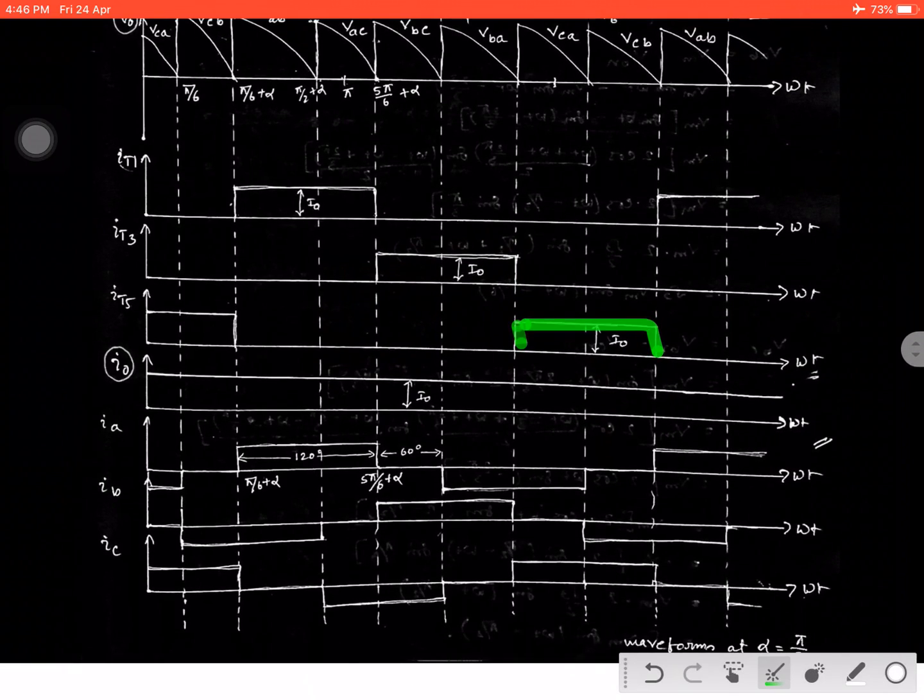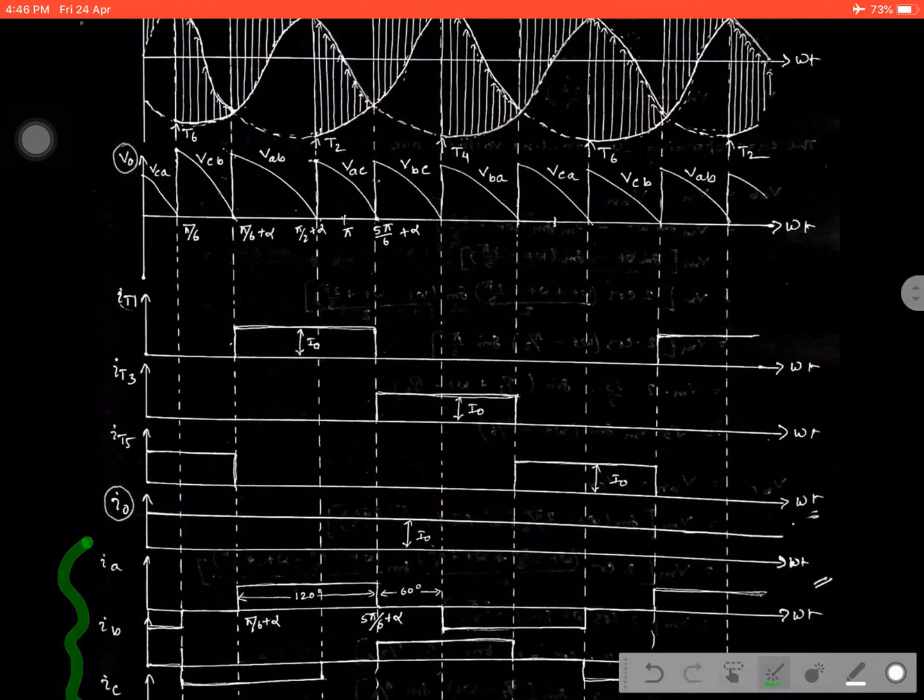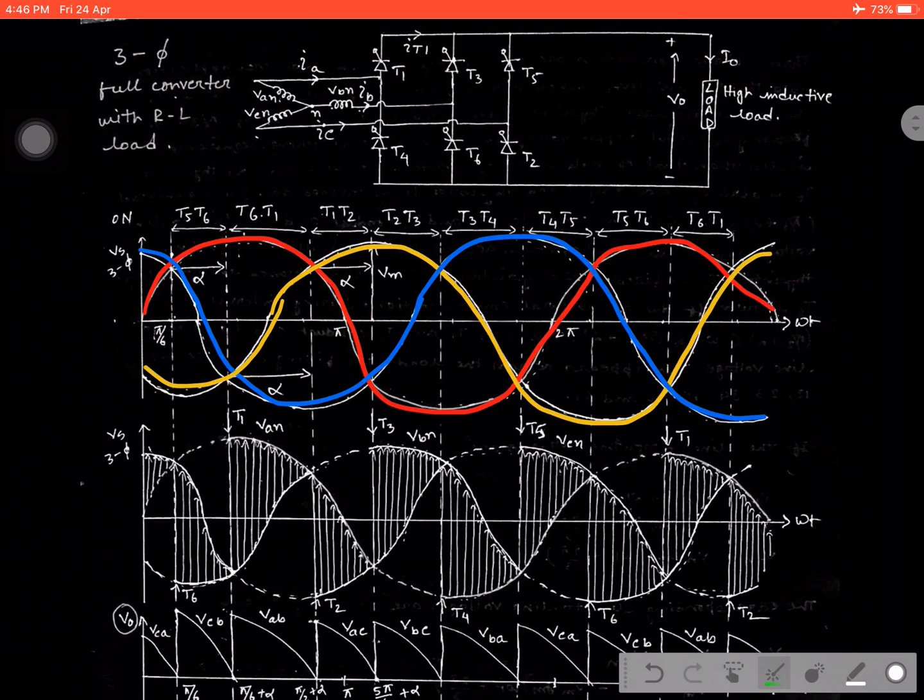So after summing these three currents, this one plus this one plus this one, which will provide you the exact DC at the output voltage, meaning the current is completely DC. Okay, so this is a good example for using a three-phase full wave rectifier, and this is all about the phase currents IA, IB, IC. Actually, we have got the voltage from the output terminal, that is actually the line voltage, and similarly for the line current.